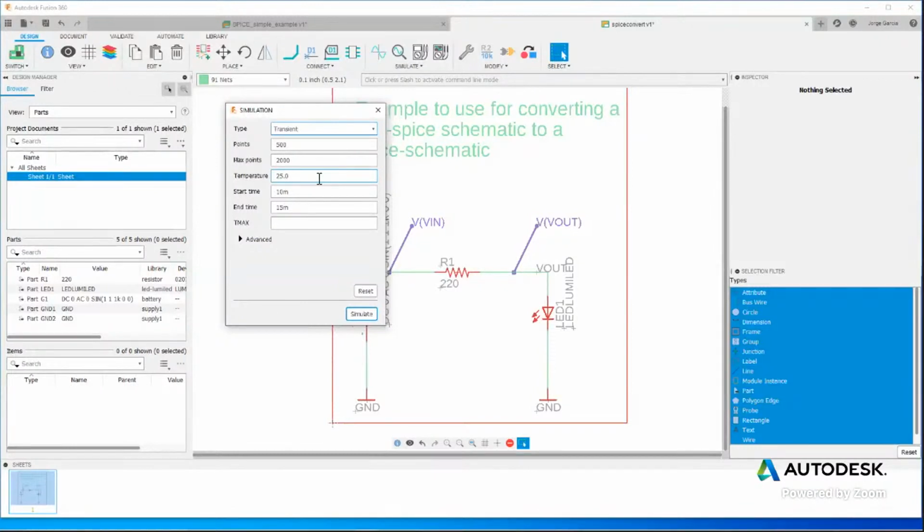So for example, resistors, as they heat up, if I recall correctly, they will tend to increase in resistance. Other components will have positive temperature coefficients, so something like a MOSFET. A MOSFET typically what will happen is as temperature increases, the resistance increases, and that limits the flow of current through them, which is actually a good behavior.